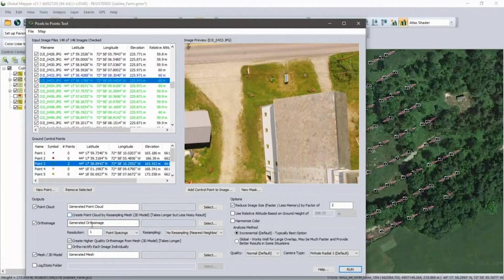We also have the option of generating an ortho image. Now, ortho image is a top-down view. That's a gridded version of the point cloud. Unlike what Mackenzie did with the single tile, which was basically take an image and ortho rectify that, this is a version of the data that is a rasterized version of the point cloud. By definition, an ortho image is an image where every pixel is correct in horizontal geographic space.